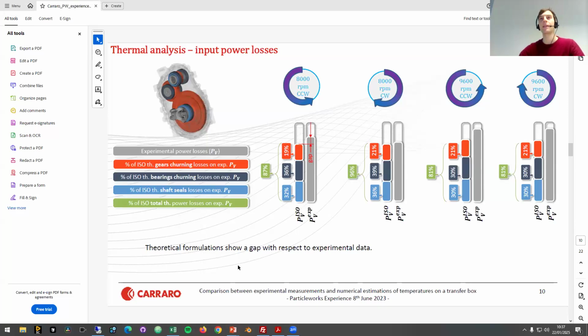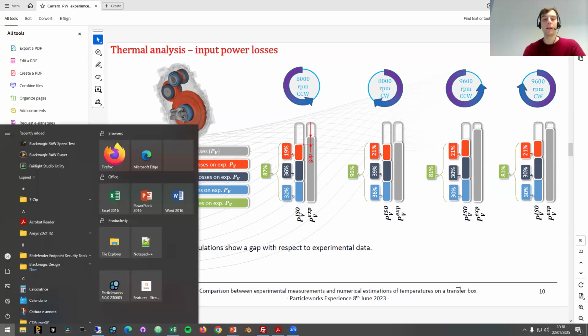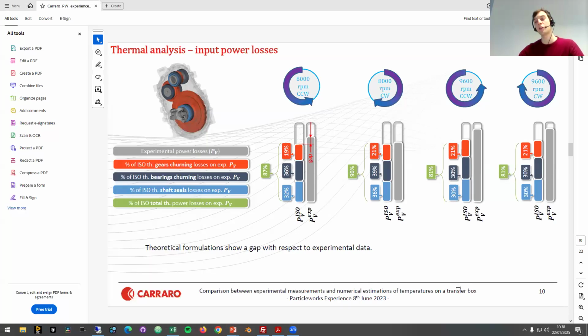There is an interface that really helps, and it's a pre-built coupling. The exchange of information, like forces of fluid on the solid, or solid position with respect to the fluid, is transferred during the simulation automatically by the coupling of the two softwares.